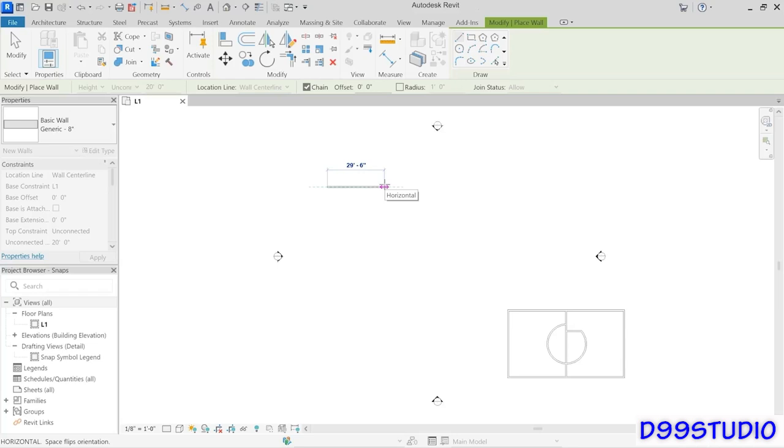Okay. Now I'm going to roll the wheel down a few clicks to zoom out. And you'll notice that that has an impact on that snap increment. So now you'll see that the increment has changed to every 4 feet. Now the increments are slightly different in the metric file, but you should witness the same behavior. The further out you're zoomed, it will use a much coarser increment, and the closer in you zoom, it'll use a much more detailed increment.